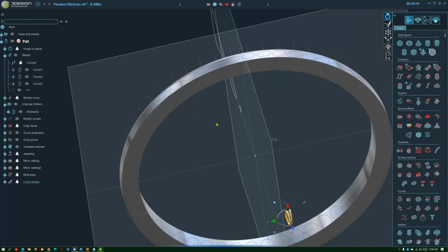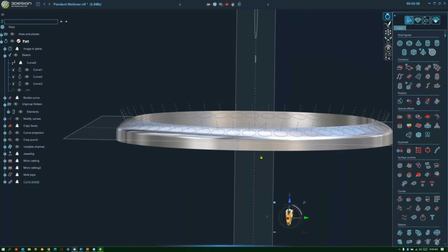Yeah, Robert says you can also use the sweeping wizard for this. Yes, definitely you can use the sweeping wizard. I could have done that and actually scaled it properly, without having to draw it a specific size too. So don't forget about sweeping wizard. If you're doing a simple one rail sweep, you can definitely control that. And having it match the top surface, it'll follow that surface direction more closely as well.